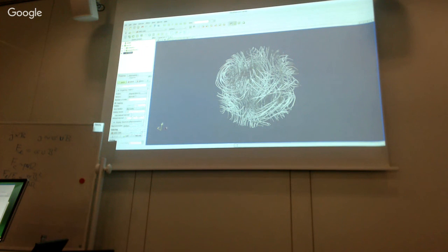So you see that here by default is angular velocity, which doesn't make sense here. So rather use magnetic energy. So why magnetic energy? And what does it tell us here? It tells us that the thickness of the field lines will depend on your local magnetic energy. So if you have a strong magnetic energy, you're gonna have thick field lines. If you have a local region where the magnetic field is very small, then you're gonna have very tiny field lines. So it's gonna emphasize the place where the magnetic field is particularly strong.